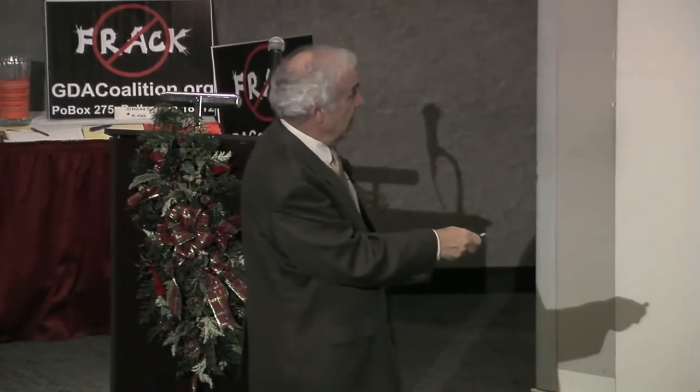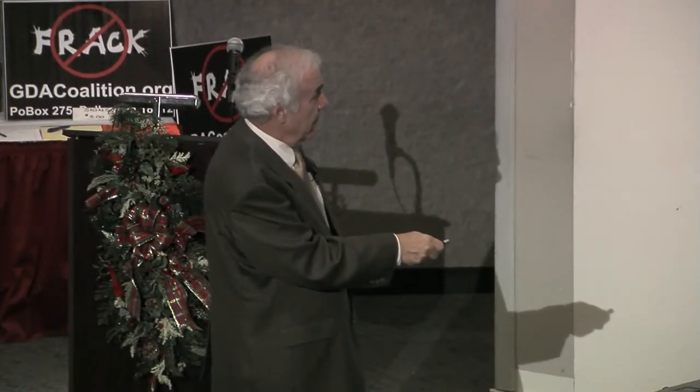So the so-called annulus that you've heard so much about, the cement problems, the bond problems between the cement and the casing, or the methane or frac fluid migration through the cement, it's important you understand the scale of things here. So if this is 8 inches of steel diameter, okay, that's 1 inch of cement. And that cement has to completely fill that annulus, otherwise you have the possibility of migration. That's a problem that's been around since this drilling process was invented back in the early 1900s.